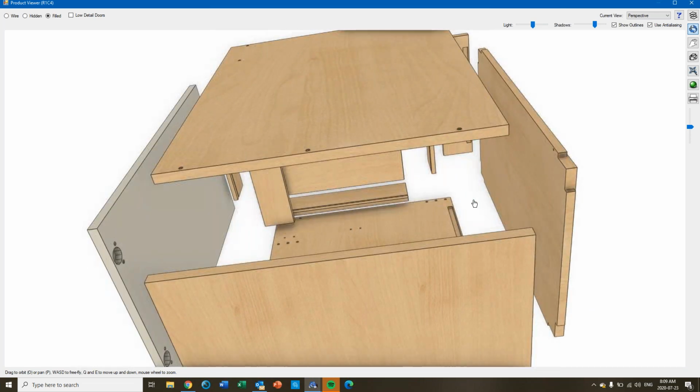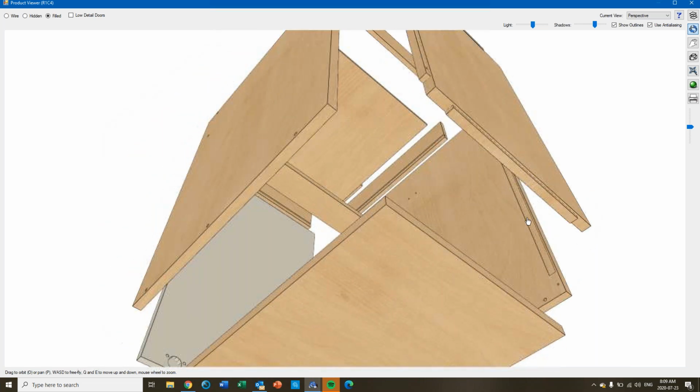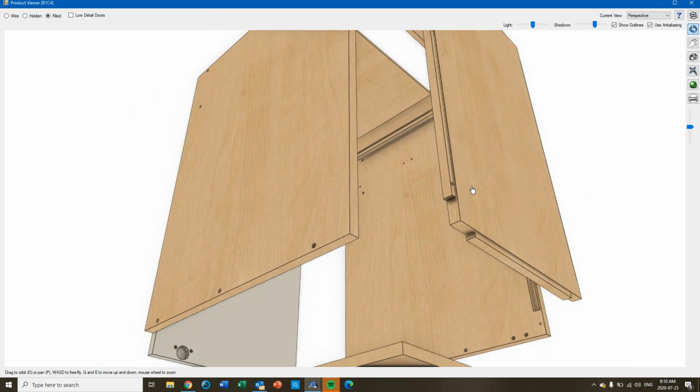Right now, Mosaic is trying to drill that hole from this side, as if I was standing here and pushed that way. When I need it to start on this side, because these dados are on the opposite side. So if I have a hole on this side and it drills through, and I have a dado on this side which doesn't go through, I have a flip side, but I can avoid it.